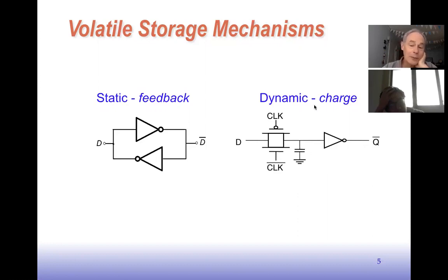In the old days, when I was a grad student designing chips, we actually built latches this way, where we didn't have feedback. We would just build a latch as shown here in this picture. You'd have a transmission gate, and you could store up a charge in a capacitor, and as long as you changed it before it leaked away, this could be a reliable way of creating a register. We tend not to do that anymore. It's very prone to noise. It's not very robust, but it is dense.